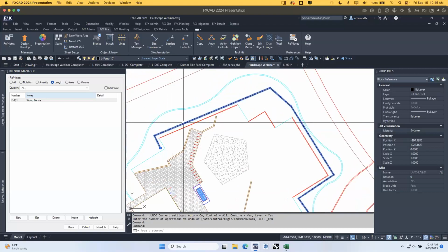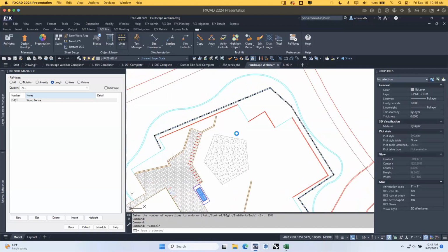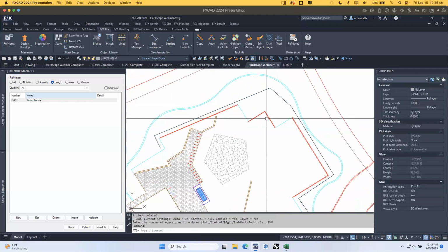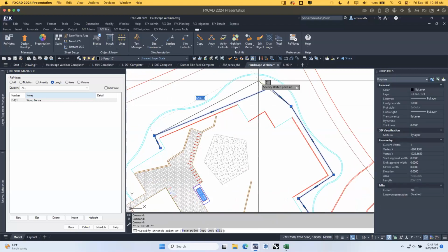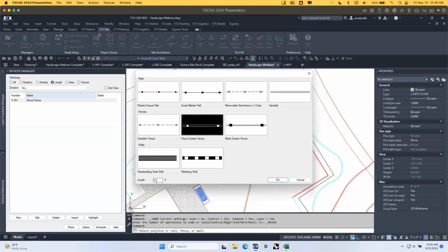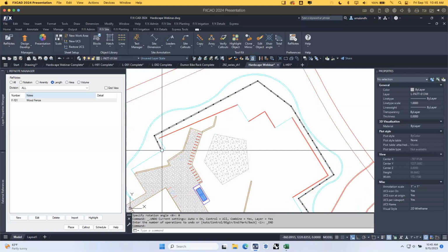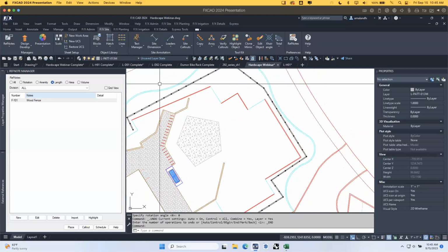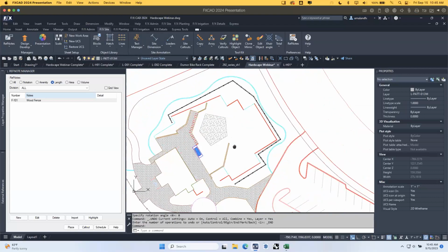And if you need to edit this at any point, all you need to do is run the railing tool. It brings it back to a polyline, and then run the railing tool on it again, select it, and say okay. We are working on some improvements to this to have a bit more memory on what it was before, and even set this to the reference note. So look out for that in the future.